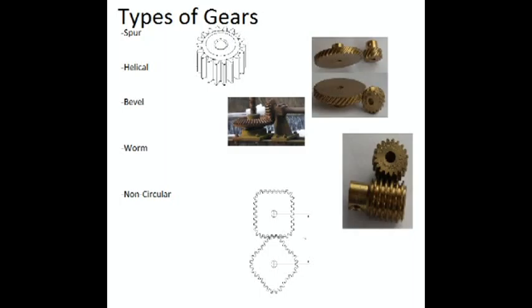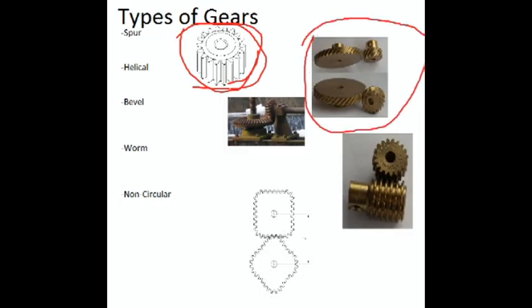There are many differing types of gears used in today's society for many different purposes. The spur gear is the simplest type of gear, shown here. They consist of a circular disc with teeth of the gear parallel to the center of the disc. Gear trains, that is, multiple connecting spur gears, can only be formed with parallel shafts in the case of this gear type. Helical gears, on the other hand, which are the most common gear, do not have teeth set parallel to the center axis, and can therefore be run in cross or parallel shaft configurations.